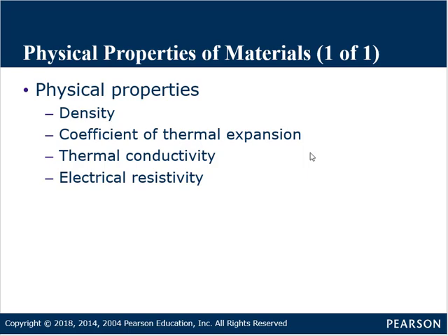So what happens is as materials are subjected to high and low temperatures, they tend to grow at higher temperatures and they tend to contract at lower temperatures. Now, since a lot of products are used over the entire operating range, you think about a bridge, okay, that bridge is out there in all environments. And you think about aircraft are out there in a lot of different environments. And so all these materials have to work together, even though they're growing and contracting with temperature at different rates. All the parts need to work together.